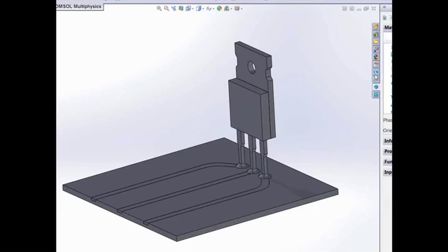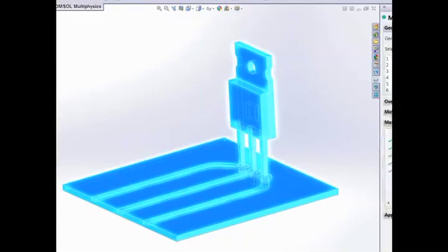So I would open up the material browser that also opens up here to the right, and a lot of this will contain copper, the pathways where the current is led, for example, and I can search for copper in our material library, and I want to add it to the model.